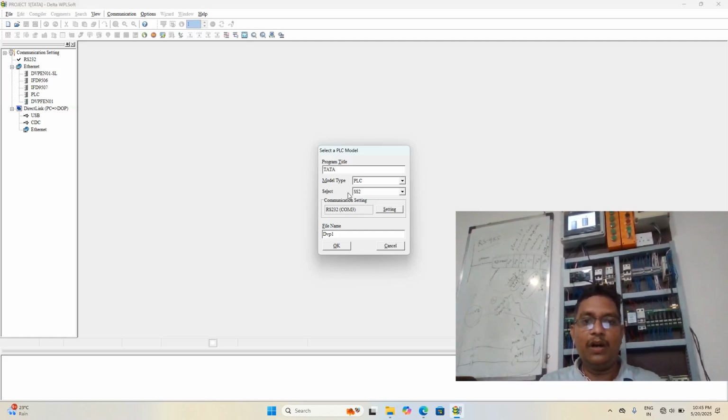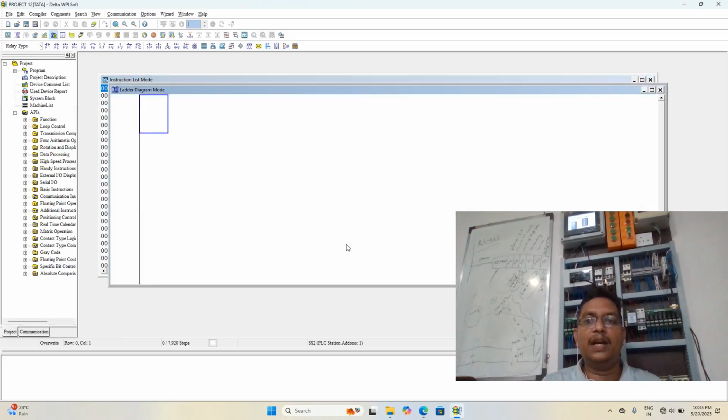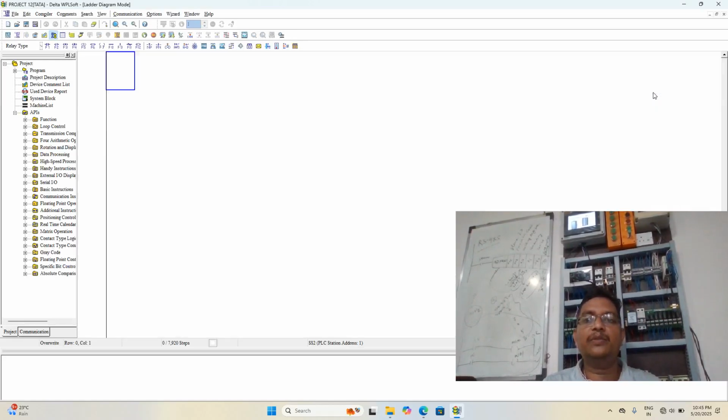So you have to select here the PLC series number, as my PLC is DVP 14SS2. SS2 is already selected here, so there is no need to change. You can type here the project name or file name. I am typing here project 12. Okay, so you can mention here as per your requirement. So I am selecting here. Now my software is ready to prepare the program.